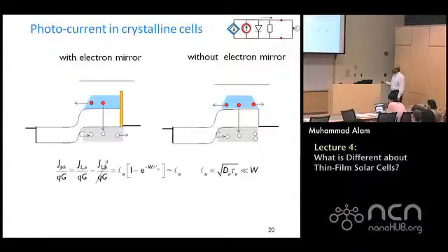So if that is the case, from the previous slide you remember, it is as if these electrons are getting out through this region, and that is what I showed in the last slide. And when you copy this same formula, you find that only the electrons within a diffusion length away from this region will be collected. The rest of them will essentially recombine here.